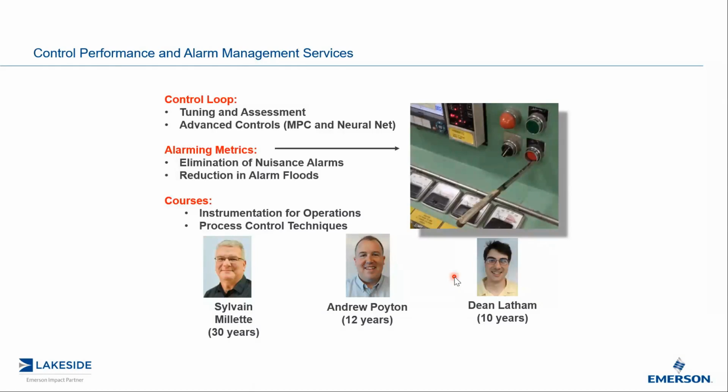And then after that, we can talk about dynamic alarming or alarm rationalization, where if a pump trips, do not alarm a low flow, do not alarm a low pressure, because they are redundant. So again, we want to make alarms relevant as opposed to eliminating them. And that is not a stock picture. That is an actual picture we took at a customer site, where they wanted to silence an alarm that kept on going off, so they used a steak knife.